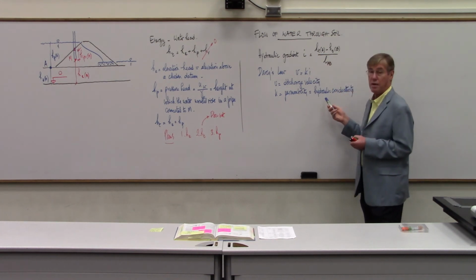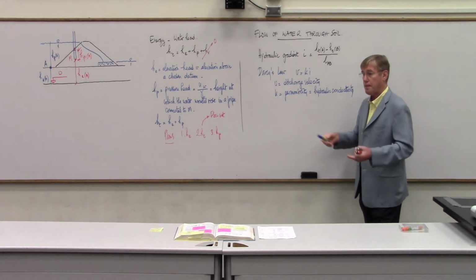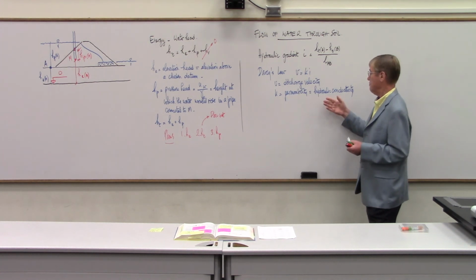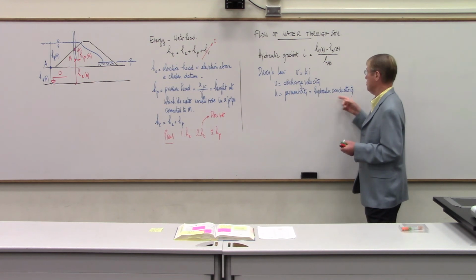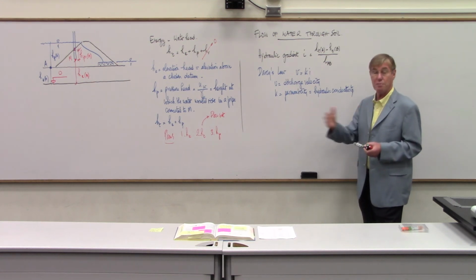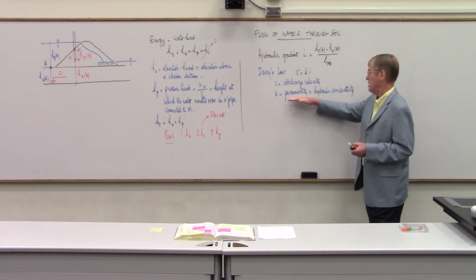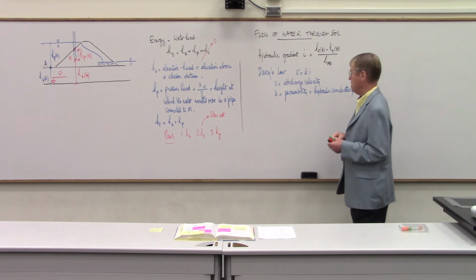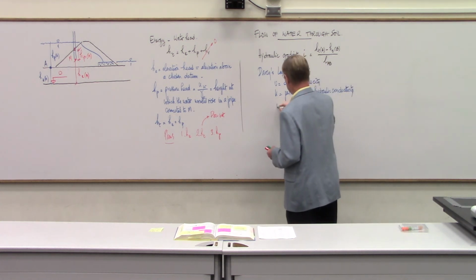it's the parallel concept to other conductivities, because there are a lot of things that flow in our engineering world. For example, flow of electricity. So you'd have electrical conductivity, flow of temperature, you'd have thermal conductivity. But in the world of geotech, we often use the word permeability. So K, and then I is the hydraulic gradient.